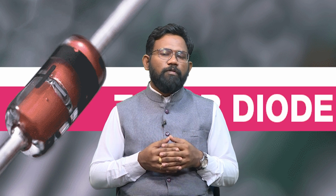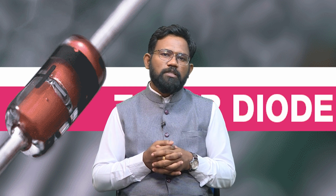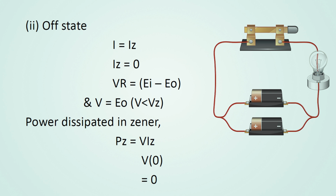During the off state, the following values will be obtained for current and voltages. The current I will be equal to IL, since IZ is equal to 0, because no current is flowing through the diode branch as it is in off condition. So, I will be equal to IL, and VR will be equal to EI minus E naught, and V is equal to E naught when the value of V is less than VZ.